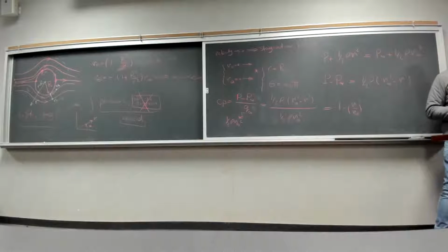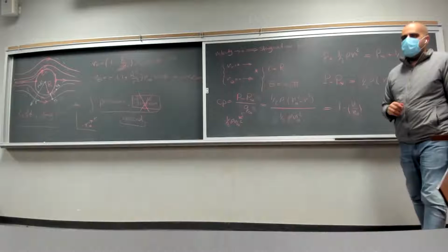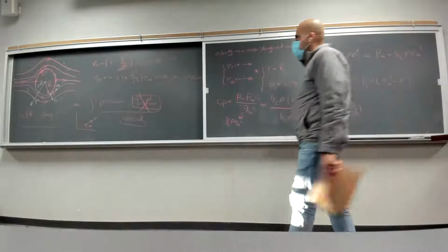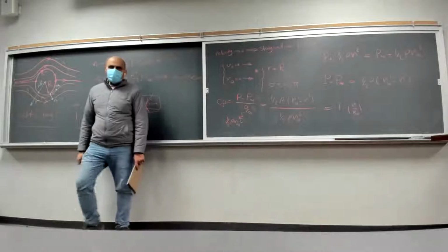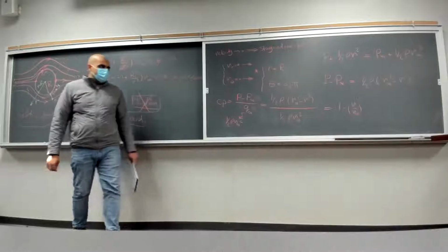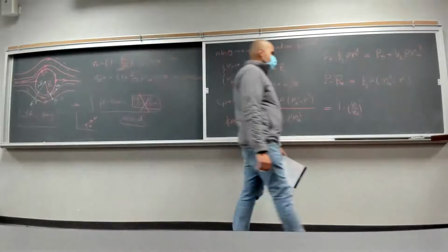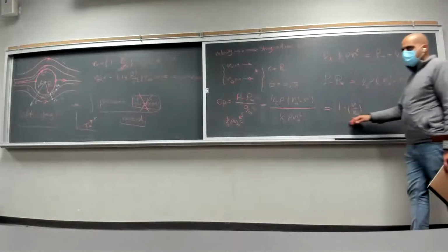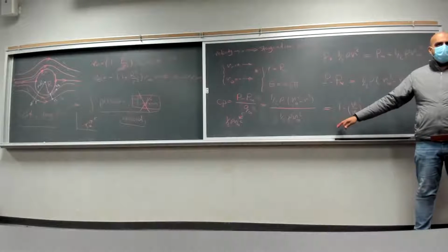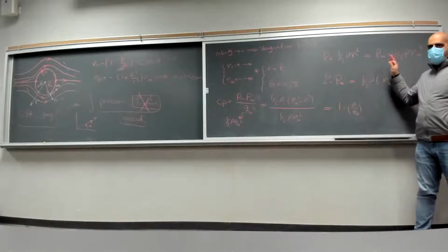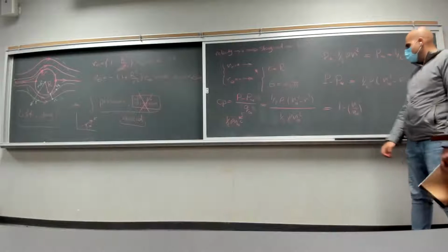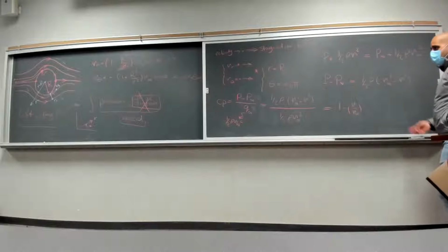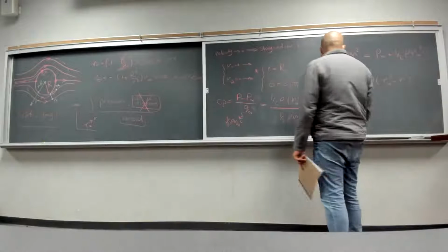So as long as we have the velocity field or velocity distribution on a surface, we will be able to find the pressure coefficient. This is true for any type of inviscid incompressible flow, as long as you can apply Bernoulli's between any two points. But for this specific flow, where we have the V infinity,